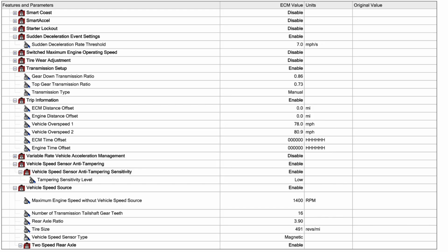And back when I talked about PTO, remember the PTO in this engine, the maximum PTO speed was 1400. That's because this setting controls that, except in alternate PTO, then it doesn't.